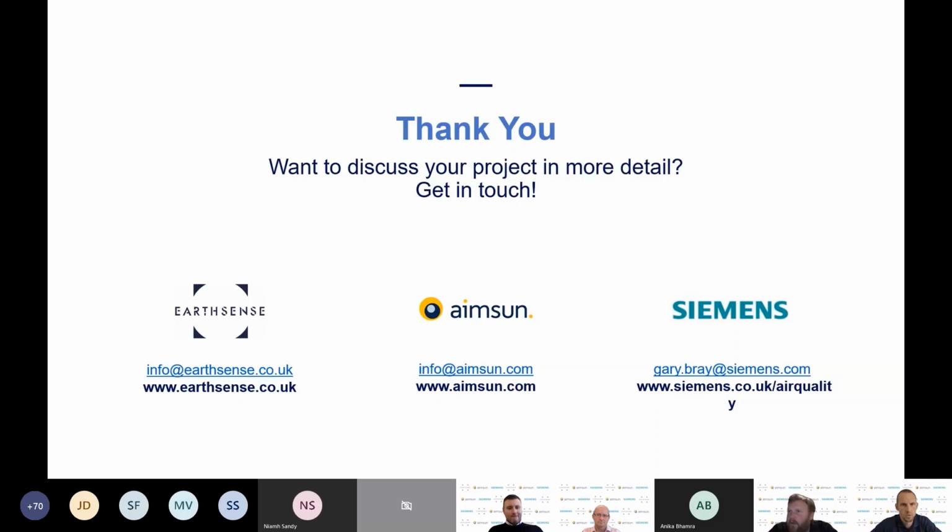Thank you. So yeah, winter mode is a 1 minute sampling instead of 10-second sampling that is put in for those units on solar panels. So not relevant in this case because they were hardwired, which is great, but it is really useful for power management. Now, because reference measurements are hourly anyway, all comparisons end up being averaged up over quite a few measurements. And I would say it's statistically insignificant, the change in agreement with a reference monitor when you are 10-second versus 1 minute. You obviously have 6 times the independent measurements, but our individual operation of the sensor over that minute is optimized so that we don't lose any more signal to noise than we absolutely have to.